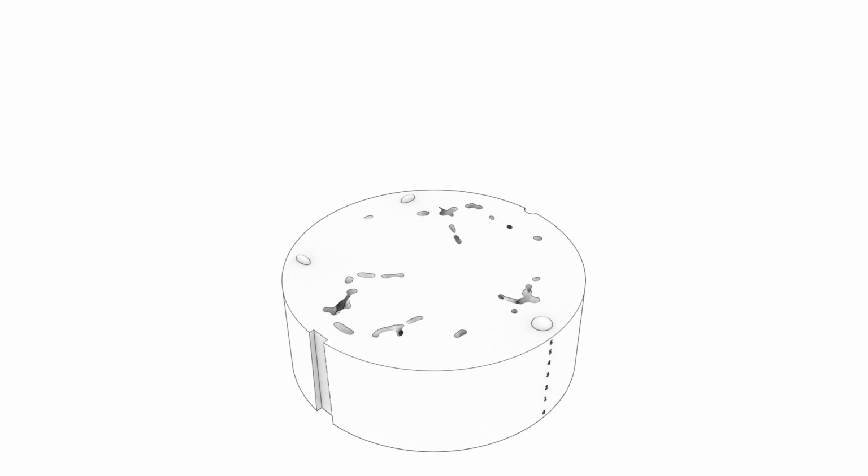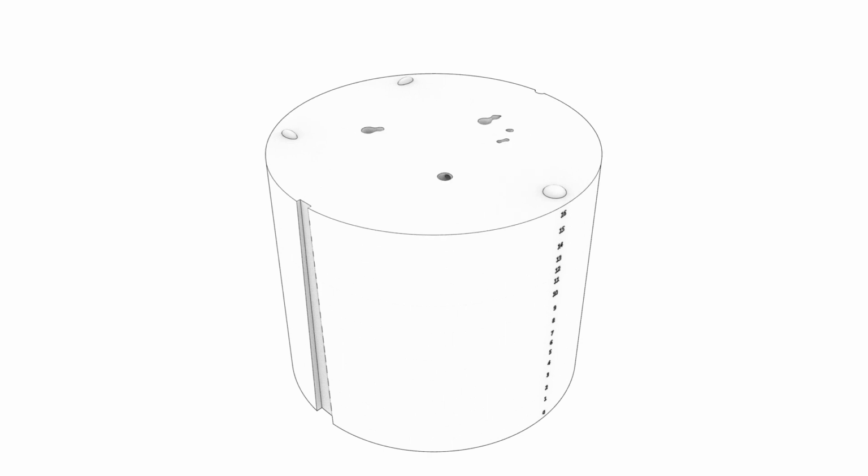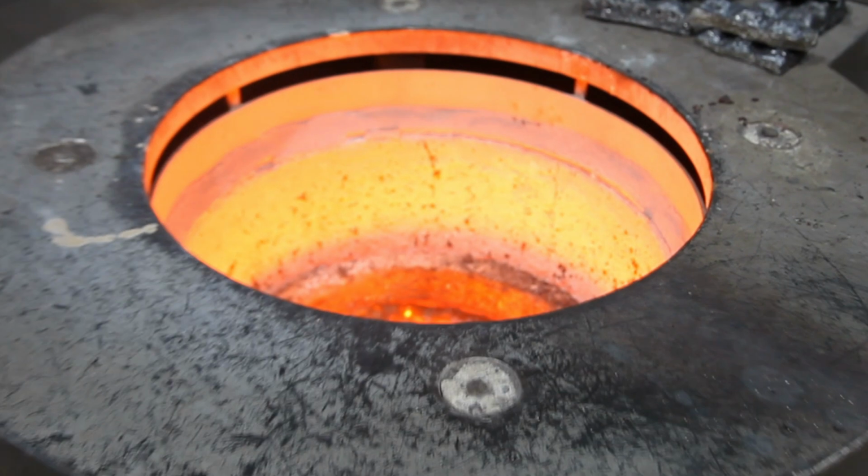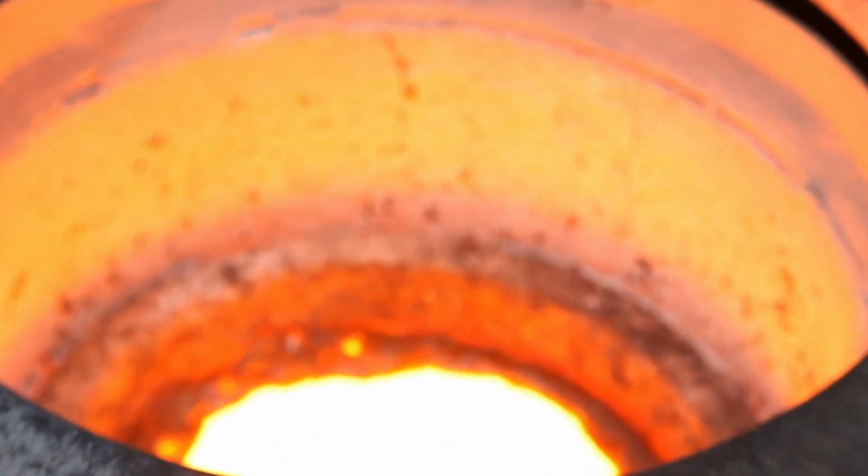The printed mold is stacked vertically from bottom to top. The liquid metal is poured from 2 legs and the other leg is used as a vent. Now, let's see how those are made with actual videos.